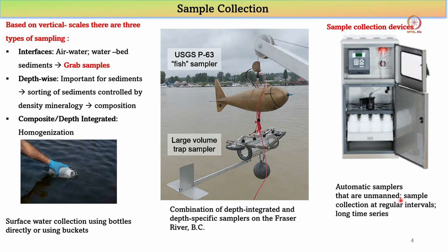But in other systems like lakes, where you have a stagnant water body, lakes can get stratified, right? So due to the stratification, we need to take water from different depths. Since there is no dynamic mixing happening all the time, that creates layers, that stratification, and different processes might be happening that give different signatures to the water.